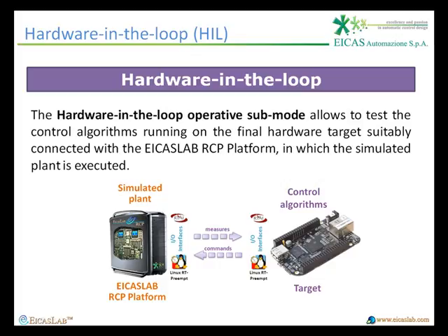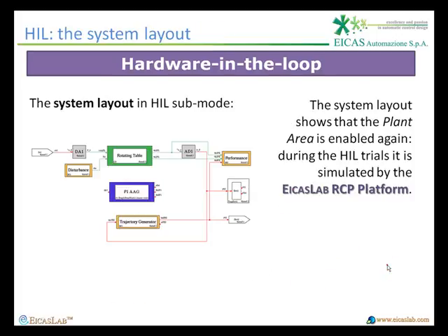Let's now consider the first target submode, the hardware-in-the-loop, which allows to test the control algorithm running on the final hardware target suitably connected with the EICASLAB RCP platform in which the simulated plant is executed. Consider now the system layout in hardware-in-the-loop submode.